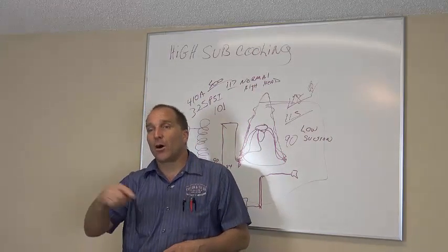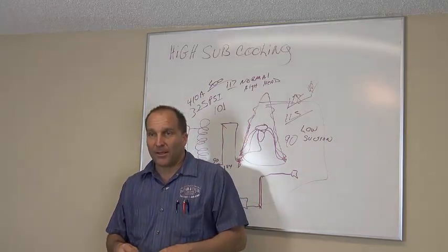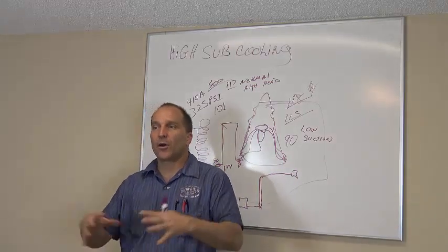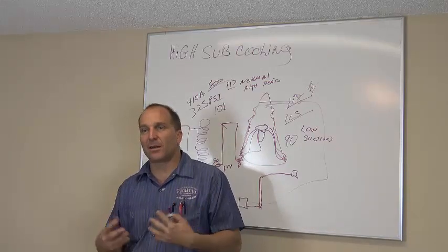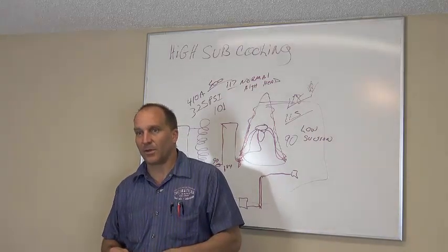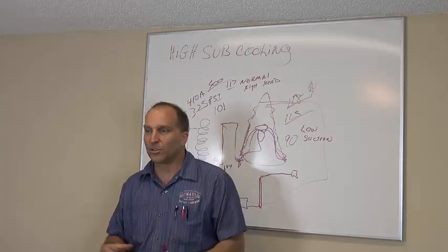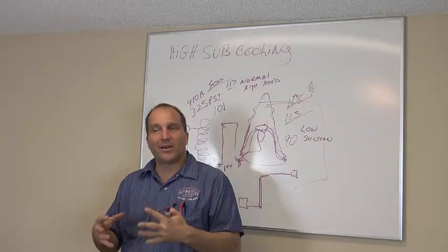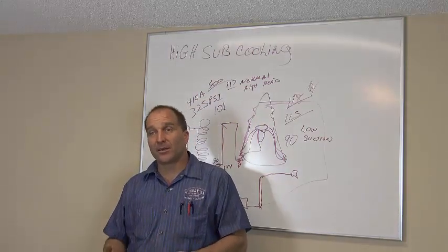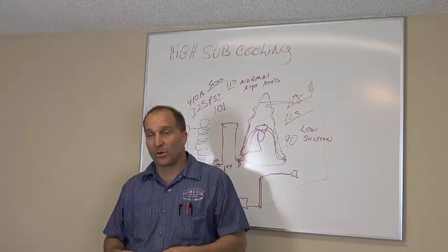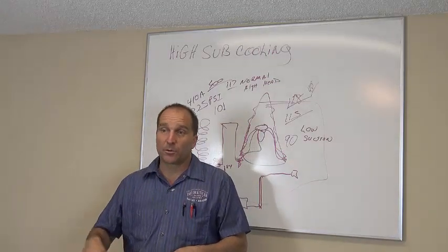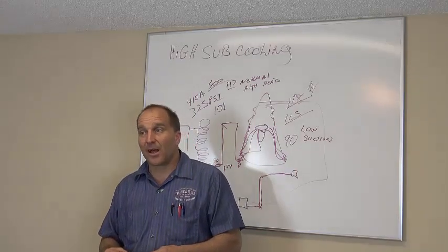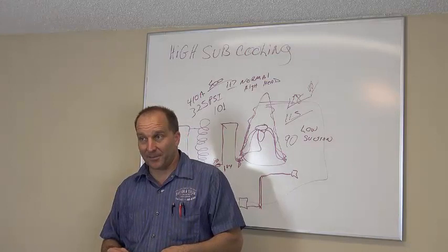If you got 3 dogs laying around that condenser, that's like 3 dogs laying around a spiked porcupine, and it sucks all the dog hair up into that porcupine. Now I've got to clean the porcupine fins out, with 3 dogs' worth of hair stuffed up into that porcupine. I see it all the time. So if you go up to an American Standard system or a Trane system or a Goodman system, it's got those spiked fins on them. You better charge a little bit extra to clean that condenser because a lot of times you got to clean it 3 times to get it clean.